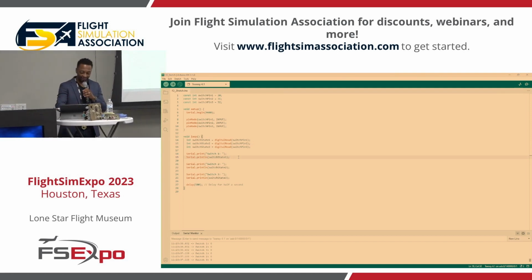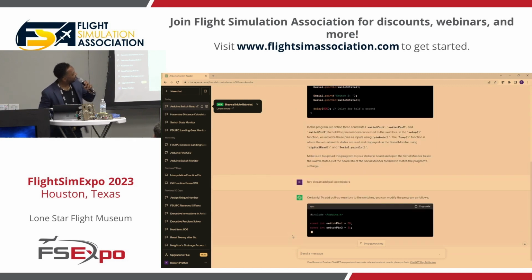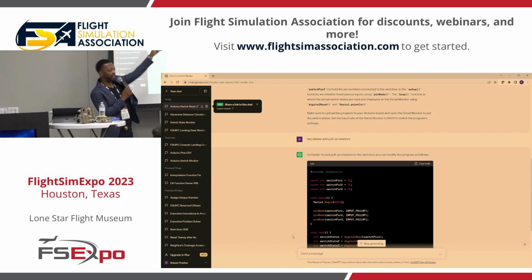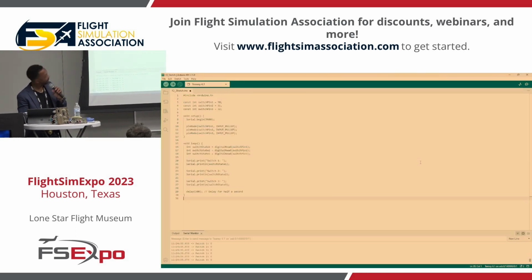So we're going to go back and have a conversation. We're going to say here, hey, please add pull-up resistors. All right. So now we told ChatGPT, please add pull-up resistors. And now it comes back and it knows that to add pull-up resistors, it has to change input to input pull-up. I'm going to copy that code, come back to my IDE, paste it in, and we're going to give this another go and see what happens.